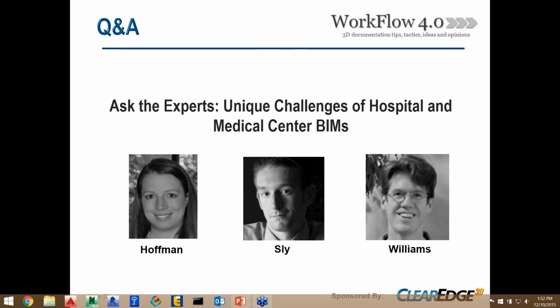So our suggestion, because we have been asked, hey, can you come out and scan? And our question is, well, is the ceiling down? If the ceiling isn't down, there's not a whole lot of value, just because of how much information you're limited to collecting, and then the lighting as well. If you're above the ceiling, you'd have to figure out ways of lighting the space to get accurate and good scans. So in my opinion, if somebody wants you to scan, you need to wait till the ceiling is demoed and then capture everything.